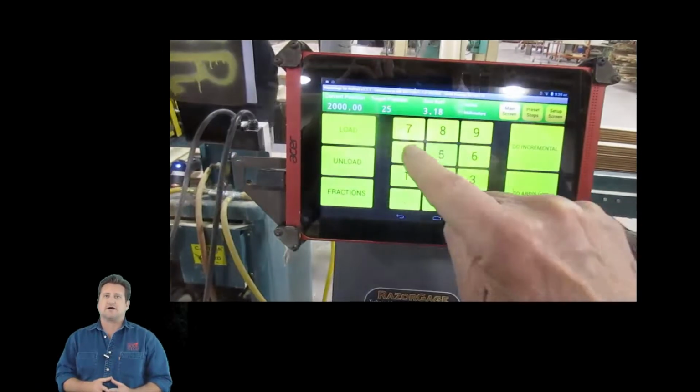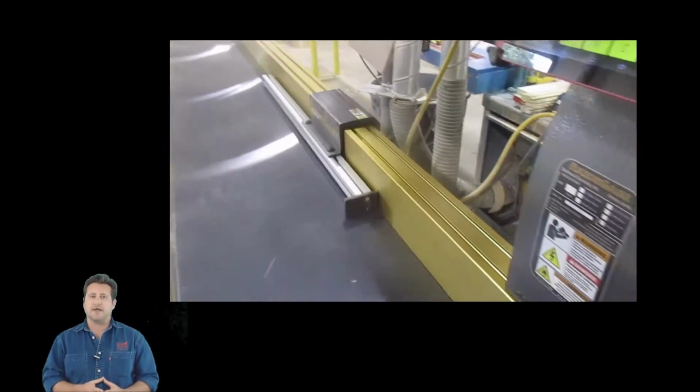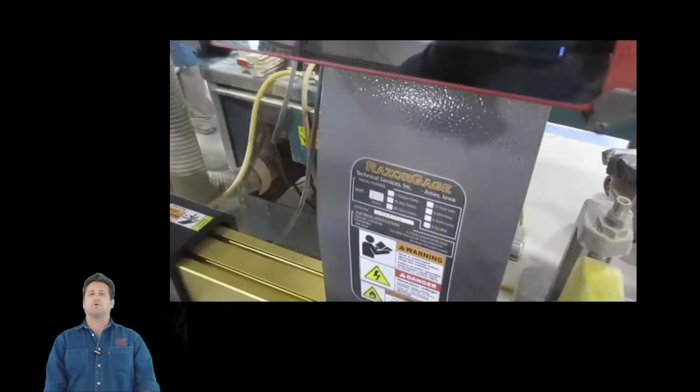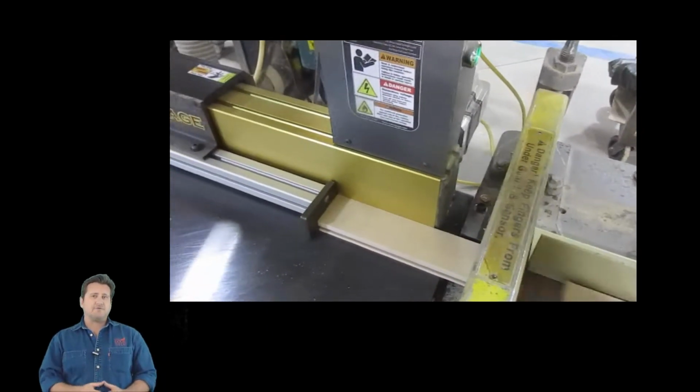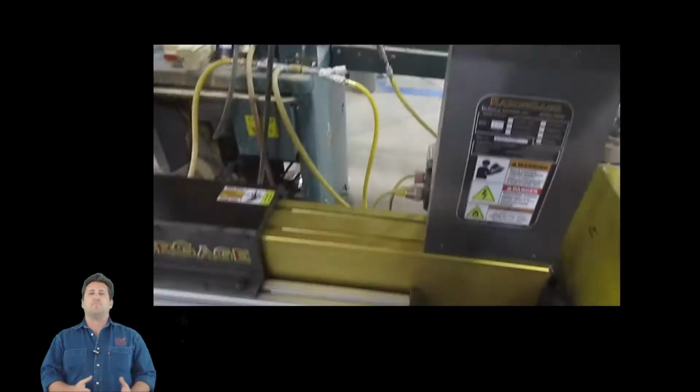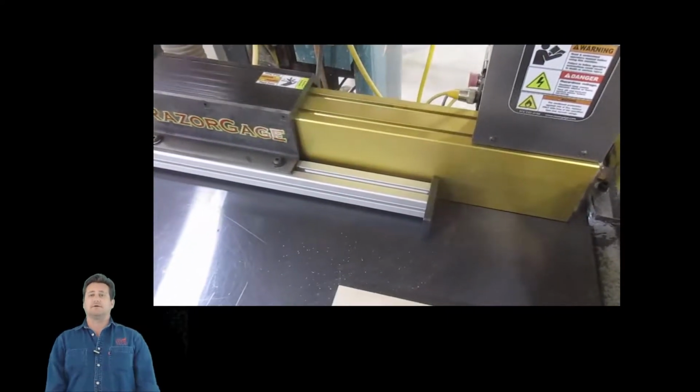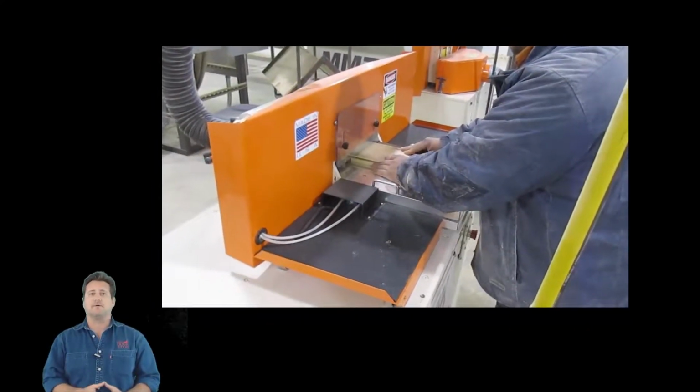Now, these shaker style stock pieces move to a computerized saw which cuts the proper lengths required for each door in the order. A video of this cutting operation is now showing. After the frame parts, called stiles and rails, are cut, the rails move to a coping station where the ends are machined, and this operation is being shown now.